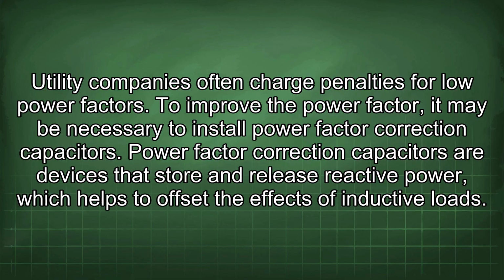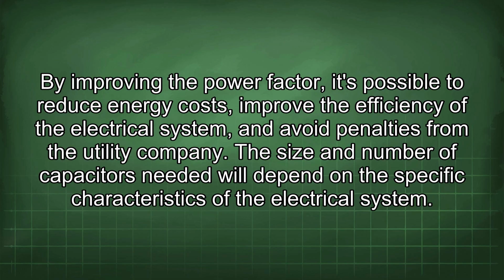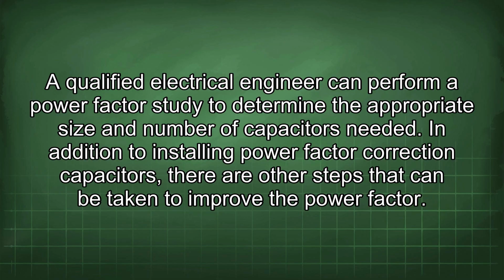To improve the power factor, it may be necessary to install power factor correction capacitors. Power factor correction capacitors are devices that store and release reactive power, which helps offset the effects of inductive loads. By improving the power factor, it's possible to reduce energy costs, improve the efficiency of the electrical system, and avoid penalties from the utility company. The size and number of capacitors needed will depend on the specific characteristics of the electrical system. A qualified electrical engineer can perform a power factor study to determine the appropriate size and number of capacitors needed.